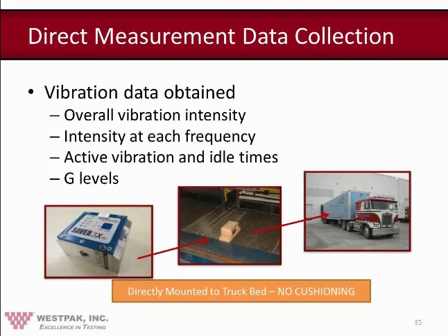At any rate, the recording of the vibration data inside of a package is not appropriate because it shows the response of the system to the vibratory input, not the actual input itself. And the input is what you're going to reproduce in the laboratory. So the data recorded shows, or should show, the overall vibration intensity at each frequency, and also the overall acceleration levels, in other words, the intensity levels, and the amount of time the vehicle is actually moving. So these are the critical things that the ride recorder would measure for distribution environment quantification.